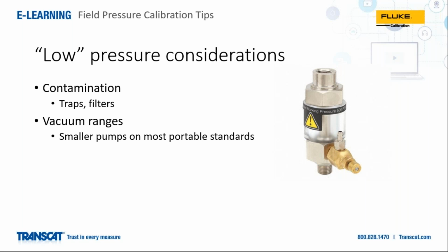In fact, in HVAC systems, differential pressure is used to sense when filters are clogged. So you can imagine that you have a filter that you're using inline for calibration. The filter becomes clogged, and now your calibrations aren't as good as they were. And so the issues with filters all revolve around filters being clogged and not knowing when it is too clogged, application dependent, too clogged to be used in the calibration system. So rule of thumb is I would steer away from filters in favor of other solutions.